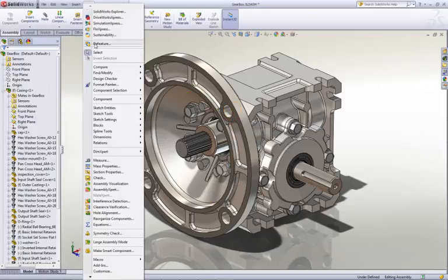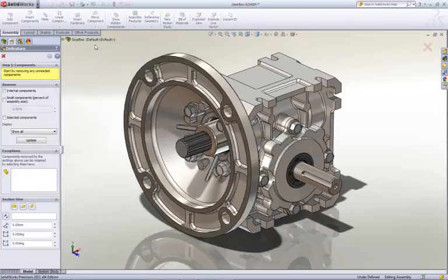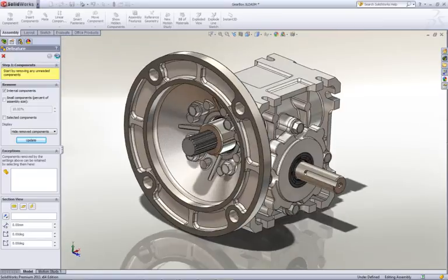To help out on this front, we've added a great new tool in Solidworks 2011 called Defeature. It's a wizard-like interface that helps us very easily go through and automatically clean up the models, whether it's based on just removing a subset of items smaller than a certain percentage, selecting specific components, or just telling it to remove everything that's internal to the model. With a couple of clicks, you can very quickly and efficiently clean up the design.